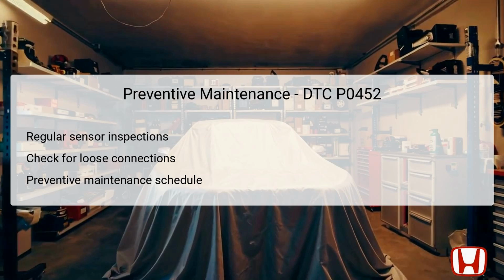Equally important is monitoring all electrical connections linked to the FTP sensor and PCM. Addressing any loose or corroded terminals can save significant repair costs down the road. Additionally, a thorough check of the entire emission system can help ensure that other components are functioning correctly and efficiently. Proactive maintenance heightens the longevity of components and reduces the likelihood of unexpected failures in the future.